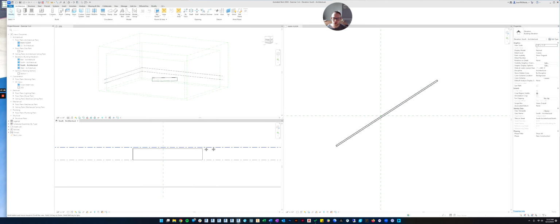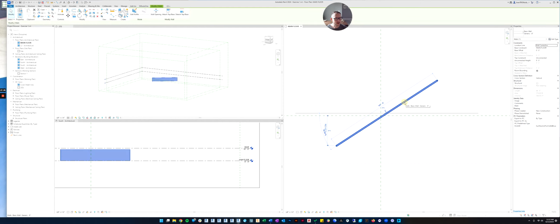So the other option you want to do is for the top constraint. Let's click the wall. Let's look at the top constraint. Instead of unconnected, let's click there and it gives us a drop-down menu. This menu will have any level that you've created in the project. Right now we only have 2, so it's only displaying 2 levels. But some projects get really complicated. There could be a basement level. There could be a foundation level.